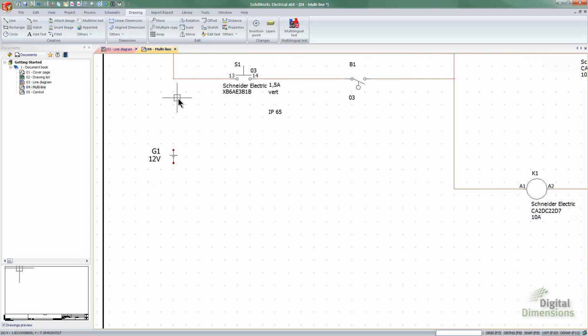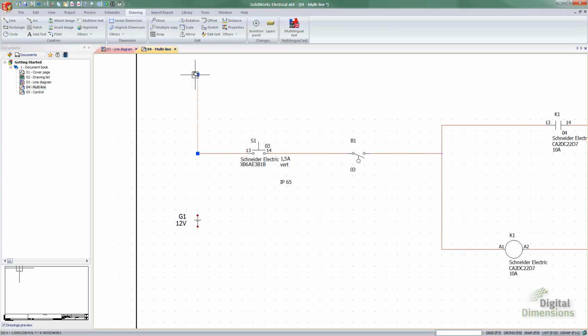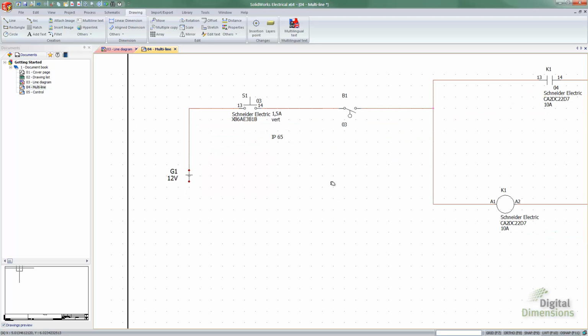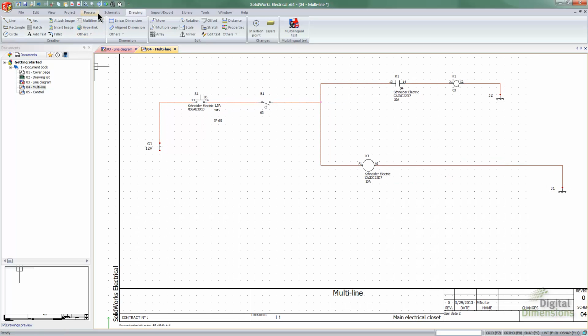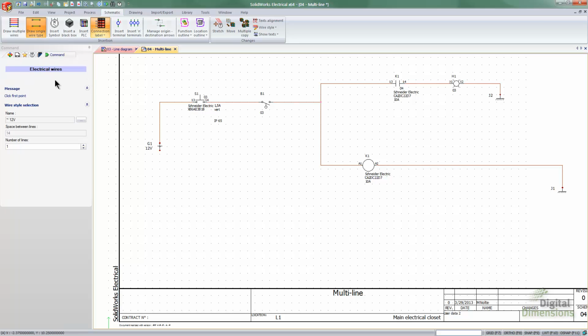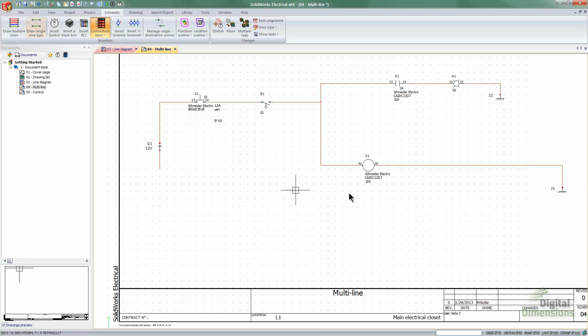Alright, so let's start finishing off our connections here. I'm going to drag this wire down until it goes down to my battery. Okay, and let's make a copy of the ground over here. I want to get a line in here first before I start dragging it. So I'm going to drag my component symbol over. If I press Control down first and then start dragging, or if I forget to hold Control, it's actually going to move it. So I have to start dragging and then press the Control button, and then it'll make me a copy. So that comes in as J3 there.